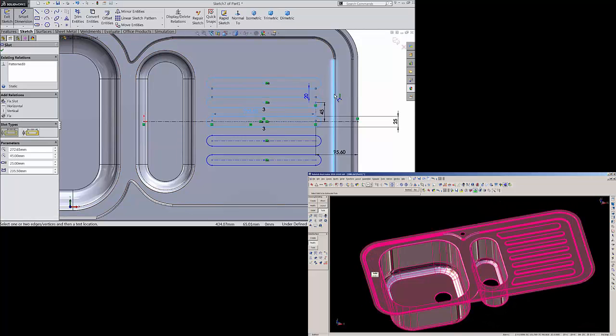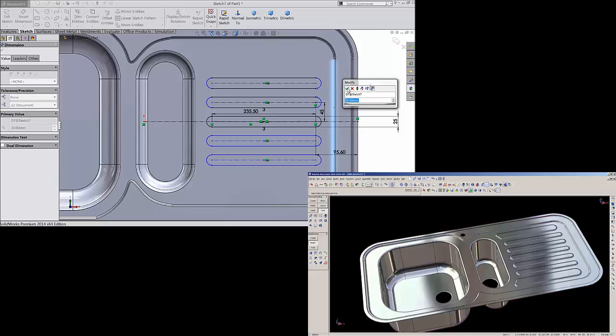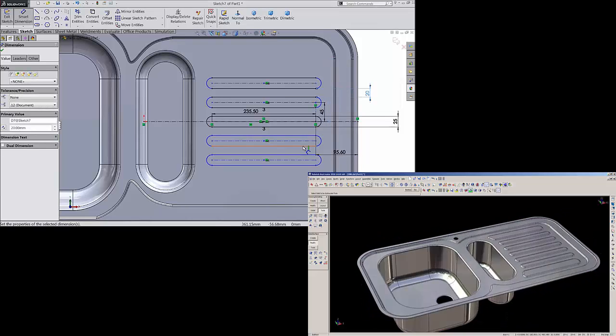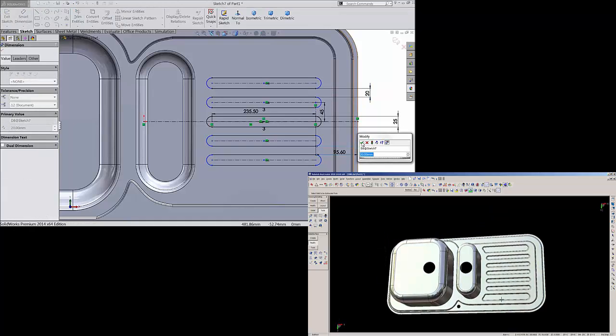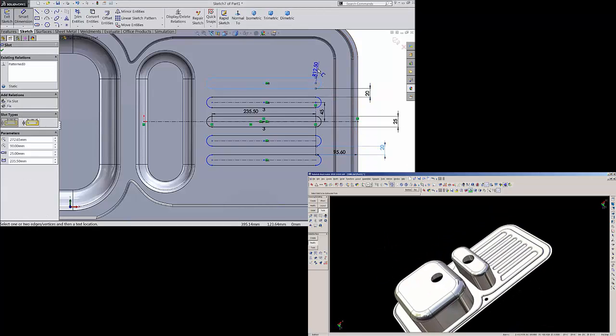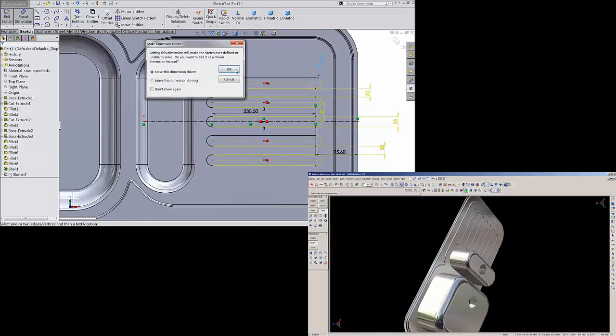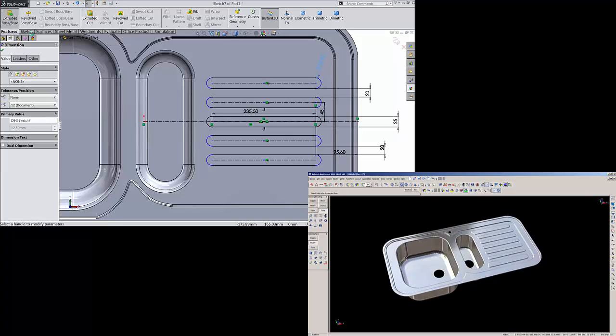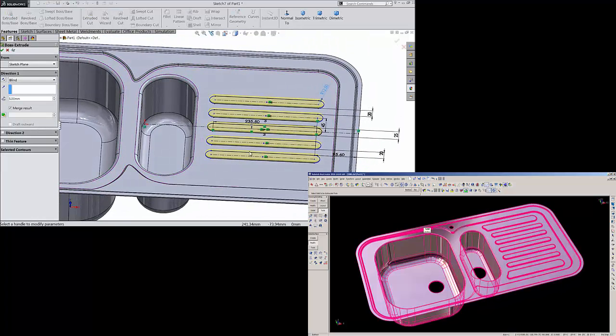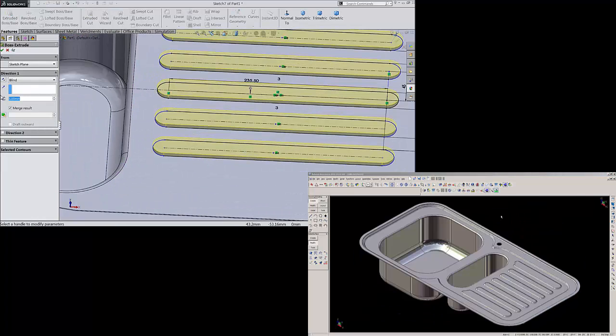Now this is our, let's check the gap between these two. It must be 20 mm. You can see it here, 20 mm, and the corner 12.5 mm. Okay, now select extruded boss and extrude up to 3 mm only.